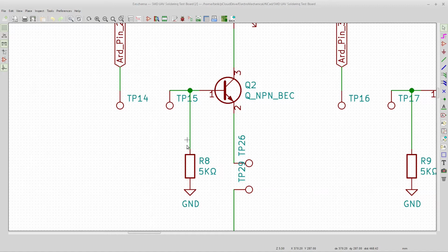So what this is, is a resistor going to ground right here. Imagine right now if we just took the resistor out. You have this pathway and you send electricity down it and it goes to this pin. If this went straight to ground, the electricity would shoot down here and straight to ground, and essentially have maybe no voltage left, no power left to turn this switch on.